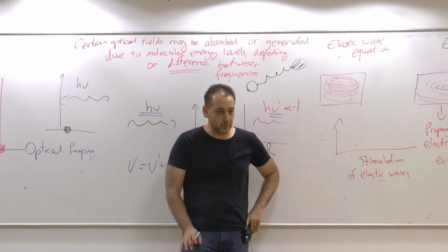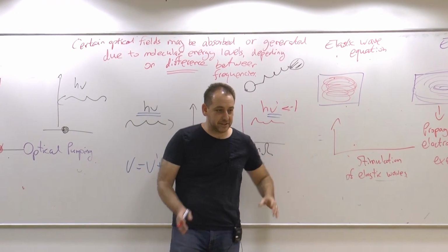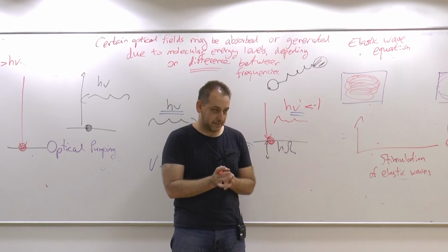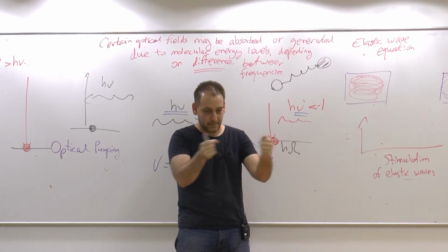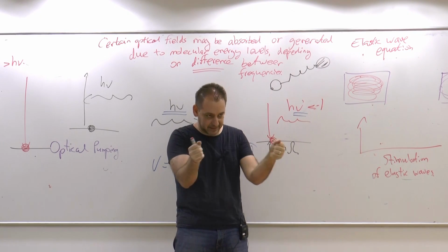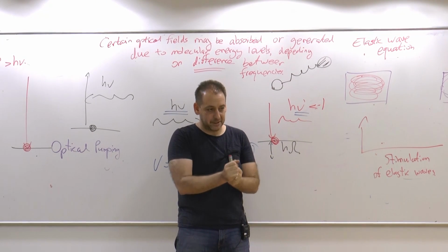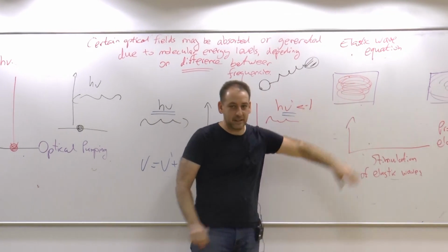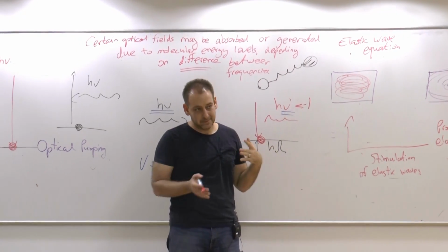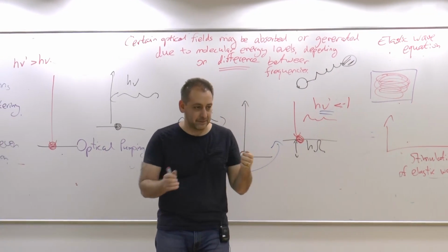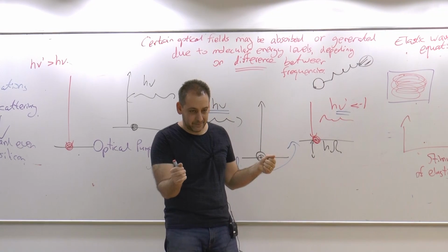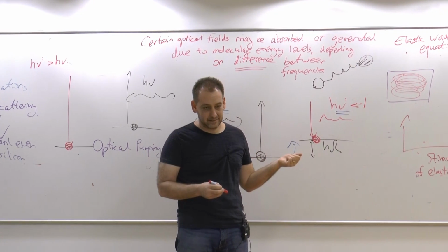Now things become even more funny, because in nature there is an effect called photoelasticity. What does this mean? That if I deform a material physically, the index changes. So the medium, this waveguide that I drew for you, at rest has a certain index, but if it now starts to oscillate elastically, the index is oscillating.